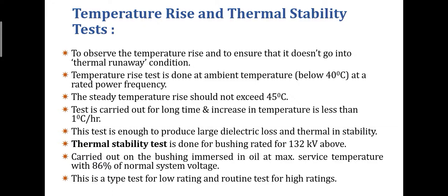The steady temperature rise should not exceed 45 degrees Celsius. That is very important. The test is carried out for a long time and the increase in temperature should be less than 1 degree Celsius per hour. This test is enough to produce large dielectric loss and thermal instability.